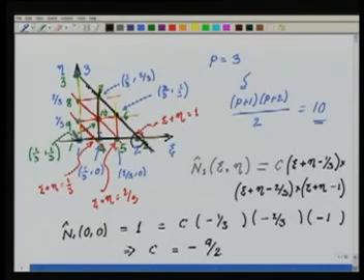Let's say N10, N10 is easy, it has to vanish on the 3 edges of the triangle. So if I have to talk of N10, N10 will be 0 along this line, which is eta equal to 0, 0 along this line, which is psi equal to 0, 0 along this line, which is psi plus eta equal to 1.